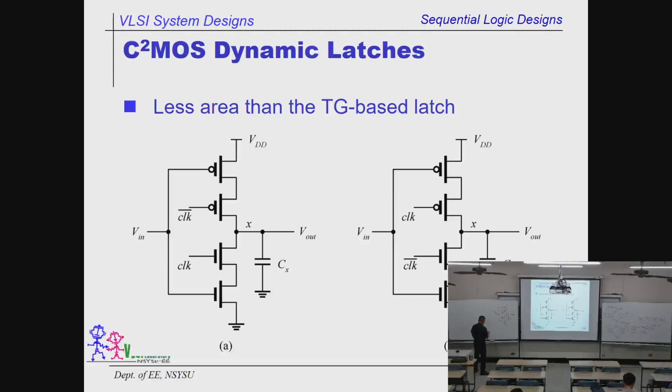Okay, now the problem is these two. Remember that we always say this is clock, and clock power shall be perfectly aligned with the clock bar. But the thing is, in most of the cases, clock goes this way, double buffered, then we take another one. This is clock, this is clock bar. Most of the cases we do this way.